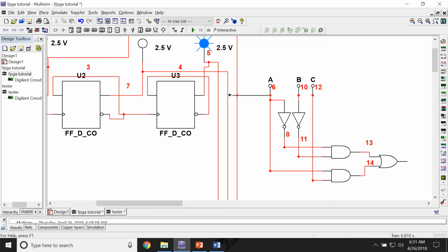So A is going to come over to the first one, which is the third flip-flop. A, third flip-flop. B, middle flip-flop. C, that flip-flop. Oh, you see, and this will happen too. This wouldn't affect it, but I just like to have everything connected. That way I know there's a, you do need to double check, because sometimes above it wouldn't matter, but below it, like if that little section went, it would matter. So now I've got that connected properly.